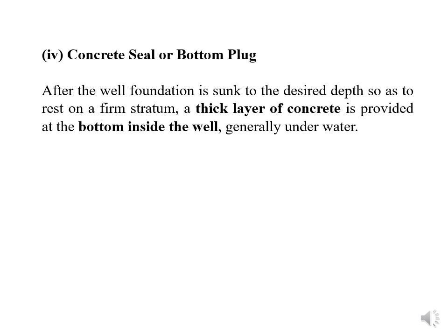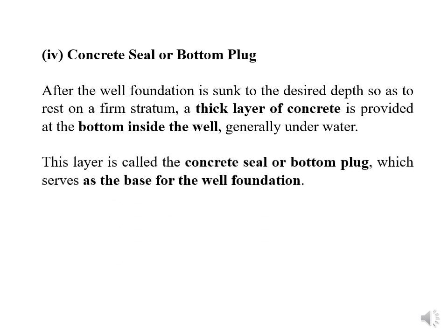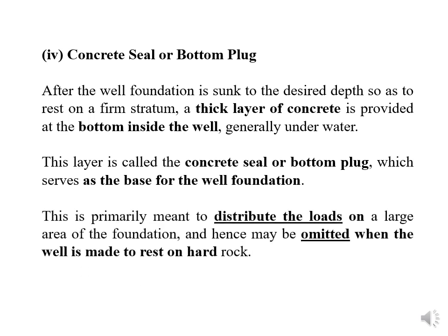A thick layer of concrete is provided at the bottom inside the well, generally underwater. This layer is called a concrete seal or bottom plug, which serves as the base for the well foundation, and then we shall fill the sand above it. What does it do?